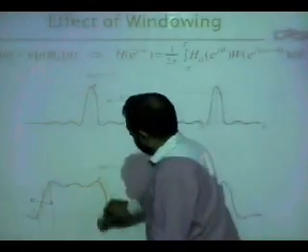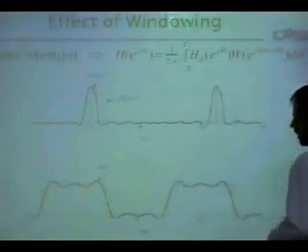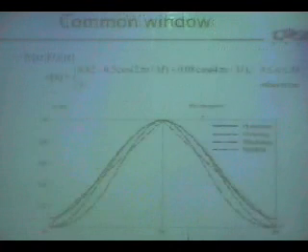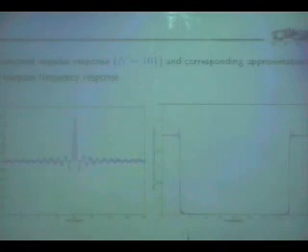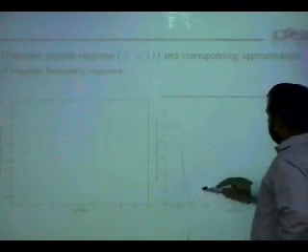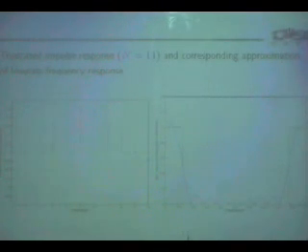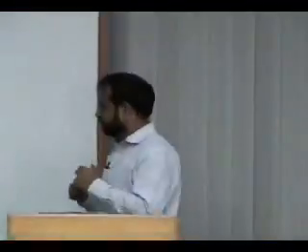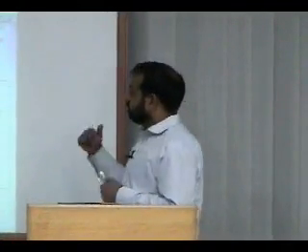Okay, so here is, to go back, this is the case. For example, for n equal to 11, you get this. Okay, and now you can see, even spending 11 coefficients, I am still not getting something very close to ideal. 11 coefficients means 11 multiplications and 10 additions.